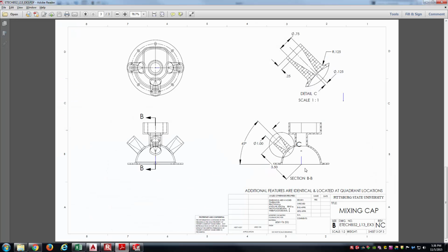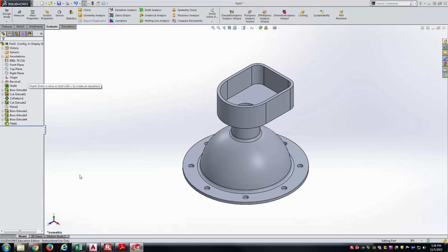Here you can see in the right view is where I've got most of the geometry definition here. So on the right plane, I'm going to start by making the sketch for the added material, and then I'll come back in and we'll use a Revolve Cut to remove the interior material there. So we're going to have a Revolve feature here where we'll add material, then a Revolve Cut to remove the unneeded material away. After that, we'll do some sort of pattern in order to create the 2 other instances here. And so that's the game plan.